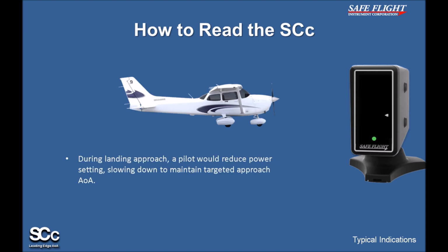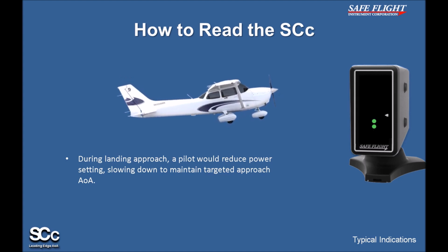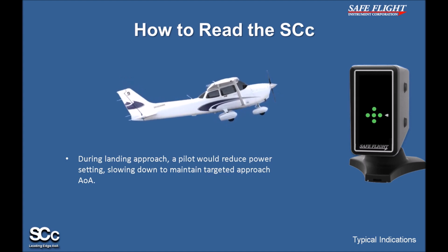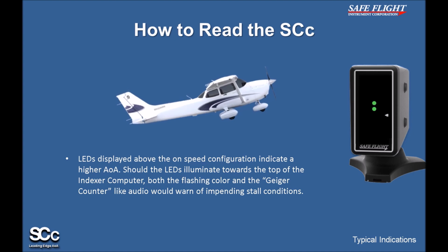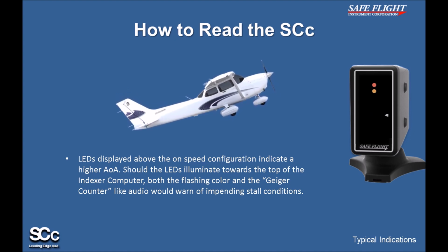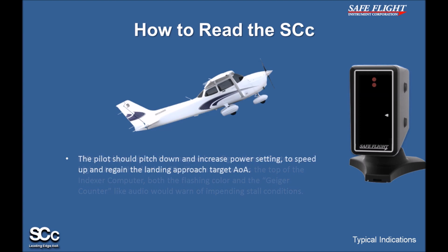During landing approach, a pilot would reduce power setting, slowing down to maintain targeted approach AoA, with the corresponding LED pattern. LEDs displayed above the on-speed configuration indicate a higher angle of attack. Should the LEDs illuminate towards the top of the Indexer computer, both the flashing color and the Geiger counter-like audio would warn of impending stall conditions. The pilot should pitch down and increase power setting to speed up and regain the landing approach target AoA.